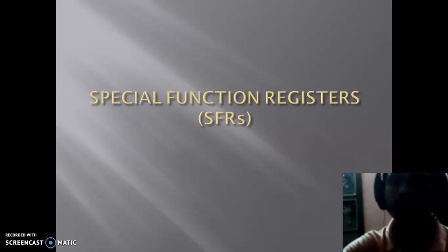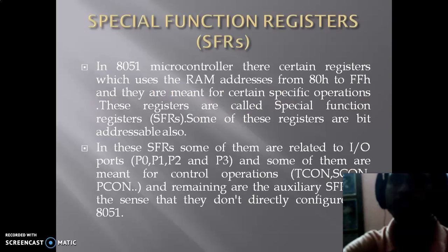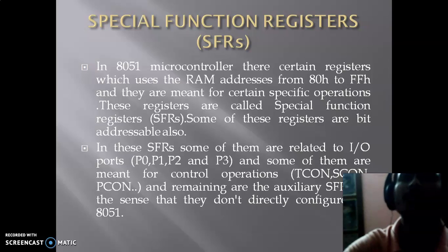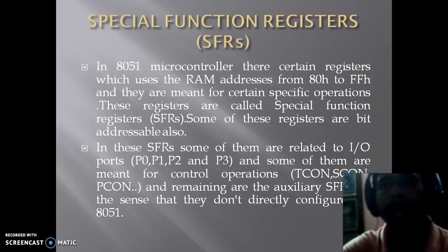Now I'm going to discuss the special function registers, SFRs. In the 8051 microcontroller, there are certain registers which use the RAM addresses from 80H to FFH, and they are meant for specific operations. These registers are called special function registers, and some of them are also bit addressable.